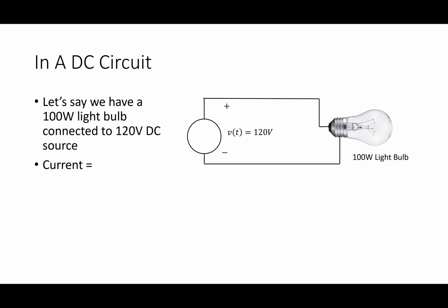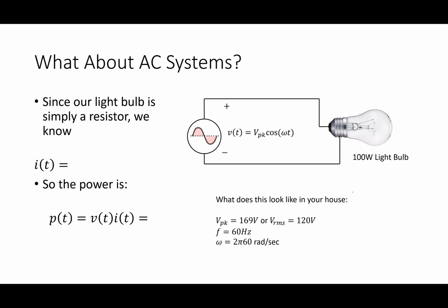100 over 120? Well, if it's power, you would say the power is equal to the voltage squared divided by the resistance, and V times I like that. So yeah, exactly what you just said. 100 divided by 120 would be the current. That should work out to be about 0.833 amps if I do that math. Pretty straightforward to do the calculation in this particular case.